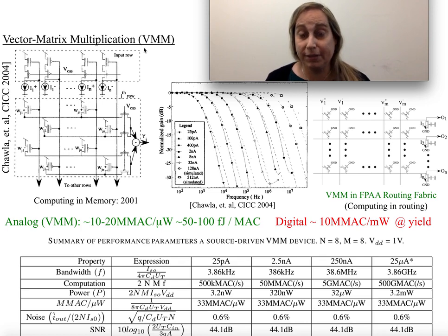If I talk about a vector matrix multiplication, this is something you need in every neural algorithm, and in many different cases. If you're going to do this in analog form, you want to be able to do it in a reasonable way. The issue traditionally was not whether I could apply a vector of signals, or take a whole bunch of multiplying elements and take all the outputs, which are currents, which is exactly what you want, because you sum all the currents together and that gives you a full output. So that's wonderful.